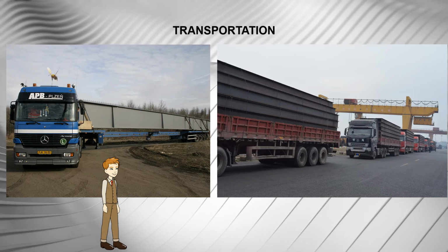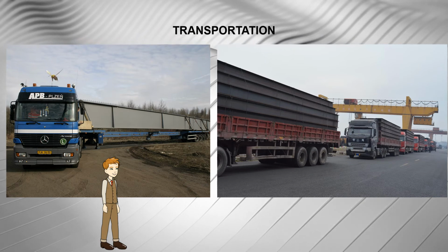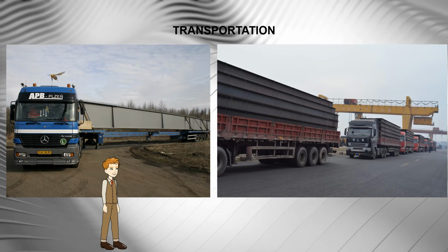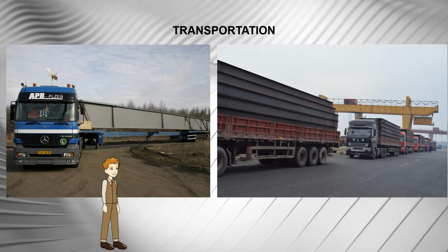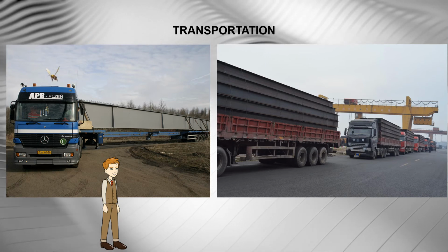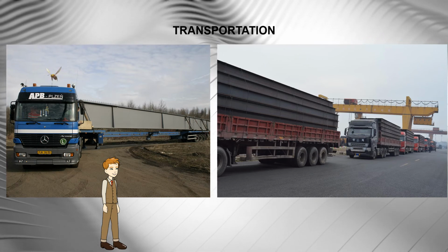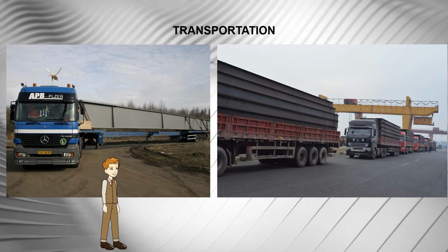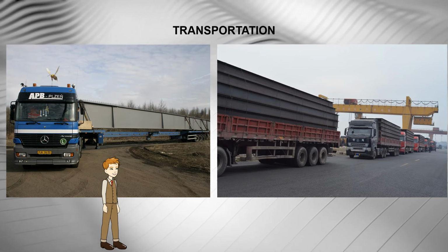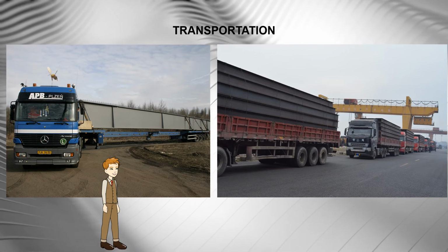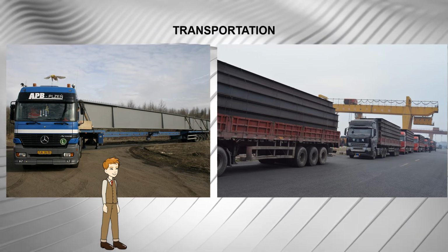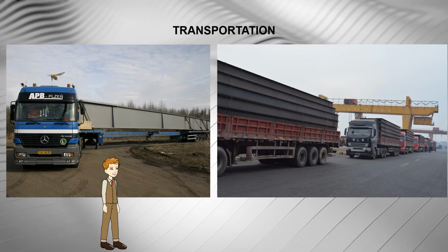Transportation. In each country, there are specific lengths and widths of structures that may be transported without any problems. Example, width up to approximately 3 meters, length up to 15 meters. For larger dimensions, a police notification or special permission is required. It should be noted that the various police authorities specify different periods when abnormal loads are allowed to move through their districts.